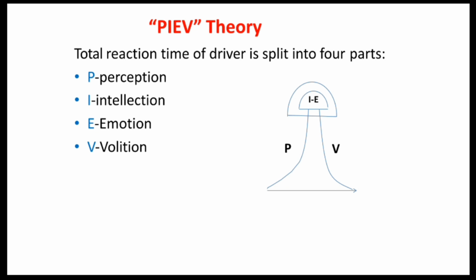Now first we shall discuss the perception time. The perception time is the time required for a driver to realize that brakes must be applied. It consists of the intellection time, which is the time required for understanding the situation. It is also the time required for comparing the different thoughts, regrouping and registering new sensations.